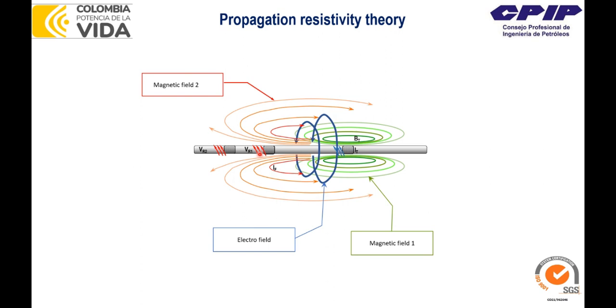But using this tilted coil, which is sensitive to one part of the well more than another, we can create the propagation resistivity azimuthal measurements, and even the deep azimuthal images. Of course, it's not the same as the density or laterolog resistivity image. It doesn't have any quantitative value, so it's quite difficult to calculate the depth.